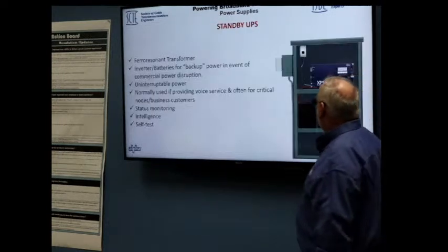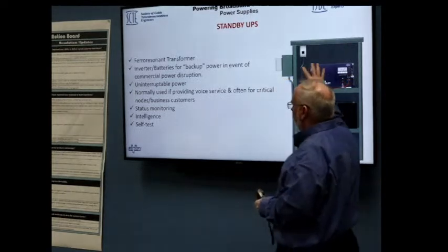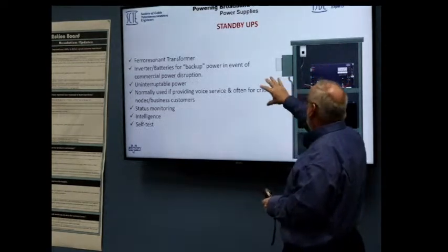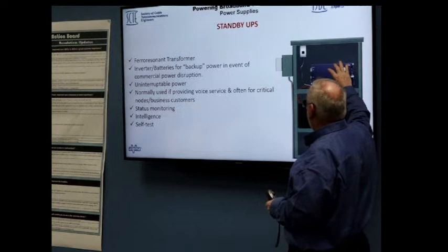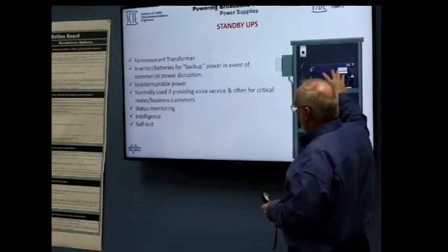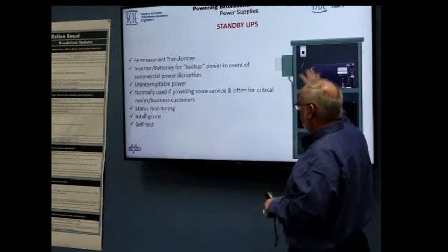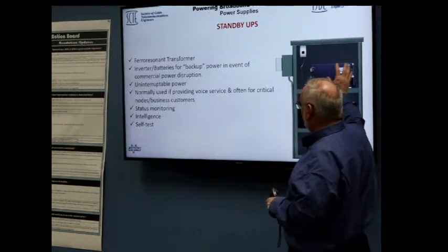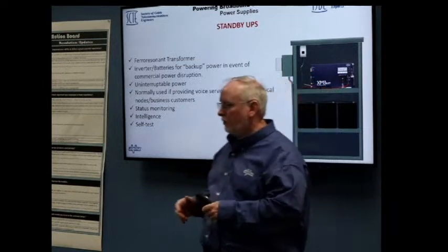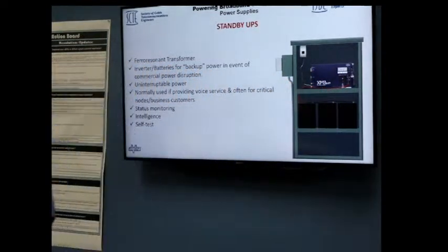So this is a standby with UPS. Again, it has the same ferroresonant transformer. It has batteries now and an inverter section, inverter charger. It provides uninterruptible power. It's optionally used for providing voice. It provides status monitoring, intelligence, and it has self-test capability.